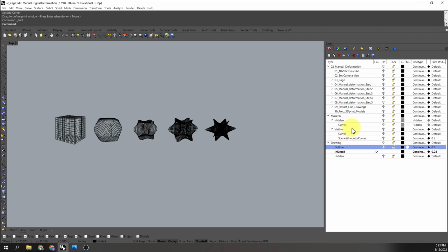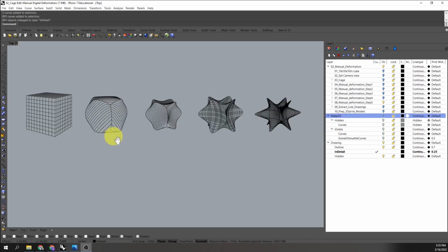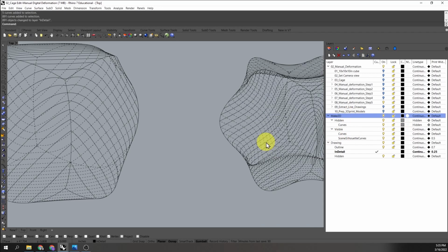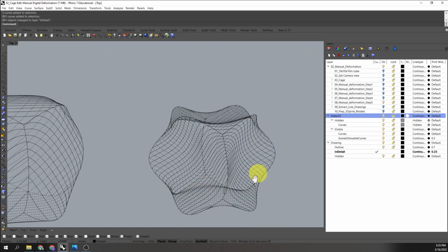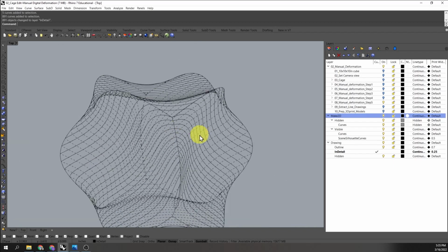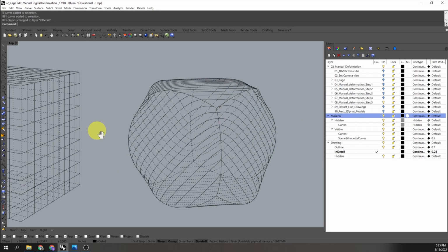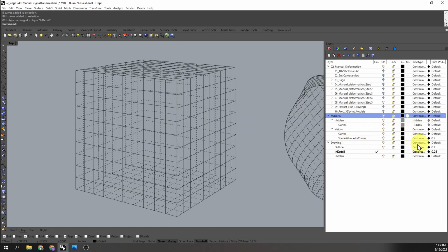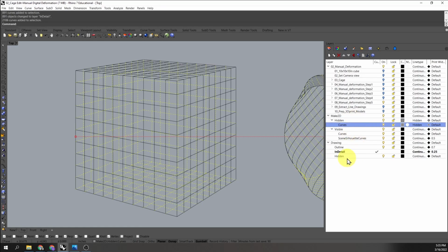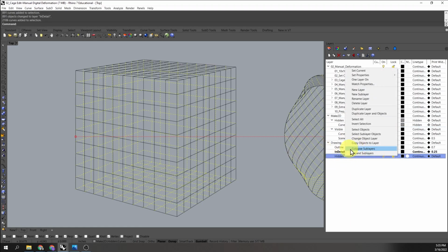So the last thing to do is these hidden lines. Now I'm going to add my hidden lines. If I go back to Make 2D and turn this on, you notice I still have those dash lines, which I particularly don't really care for. I understand for some architectural drawings this makes sense, but I'm going to go ahead and change those. I'm going to select them, right click on it, select objects, and assign them to my new hidden layer.